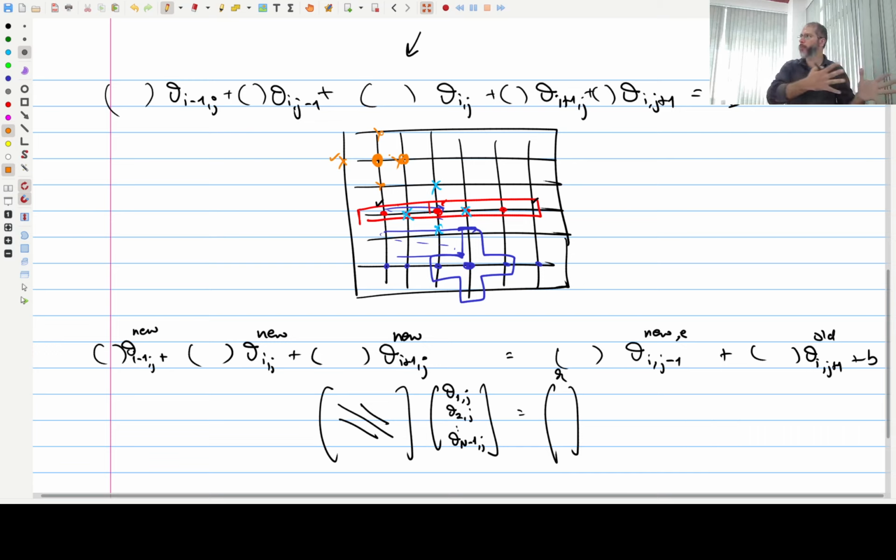It's only the left boundary information moving to the right, the way we are visiting. But if you visit the whole thing by lines, the complete information travels to the whole line. Okay? So by visiting things by line, the boundary information gets percolated or transmitted into the domain much faster. And that is the reason you get a better convergence.